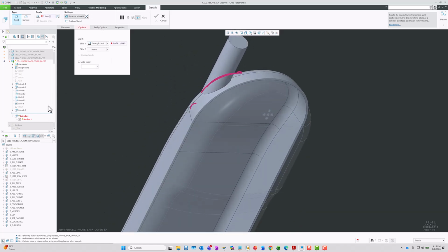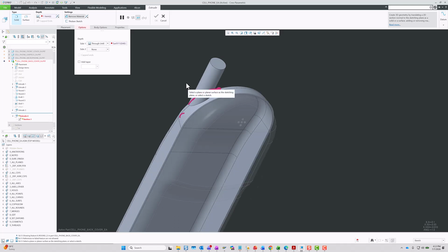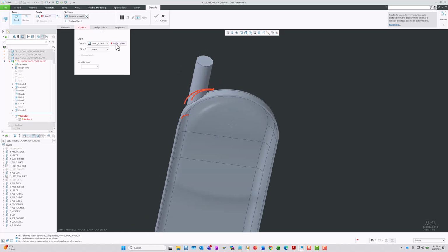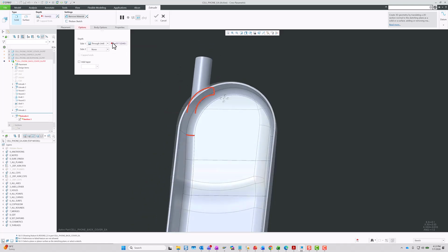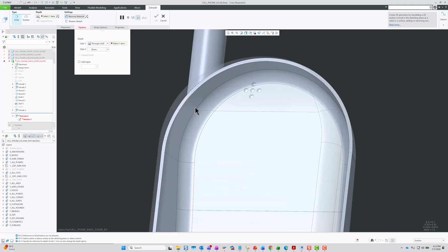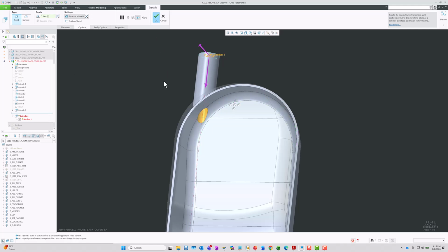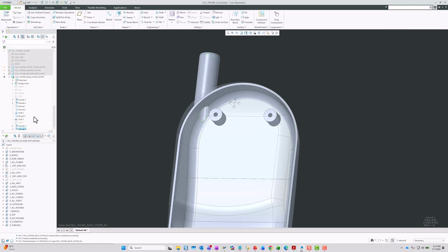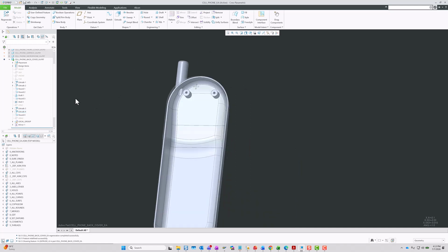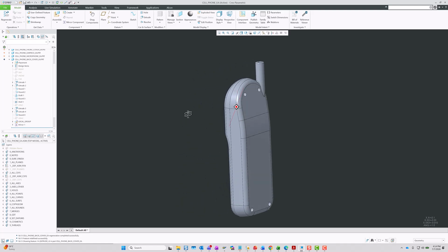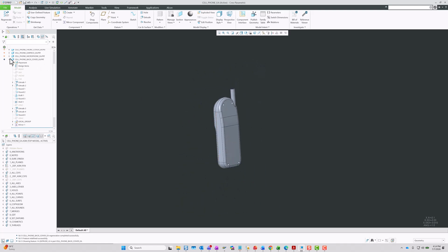This is an extrude. I think this is the hole. So let's just remove this surface and select this one. This is the hole, and accept it. So everything looks beautiful now. So with your keyboard, press Ctrl A to activate the assembly again. And now it looks good again.